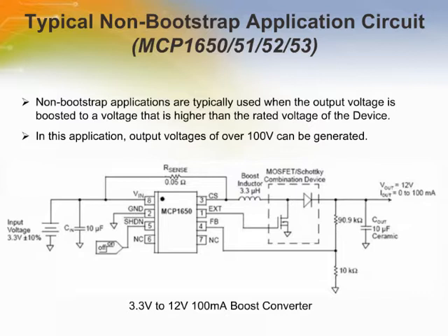The gated oscillator duty cycle will be dependent on the value of the voltage on VN. If VN is greater than 3.8 volts, the duty cycle will be 56%. If VN is less than 3.8 volts, the duty cycle will be 80%.